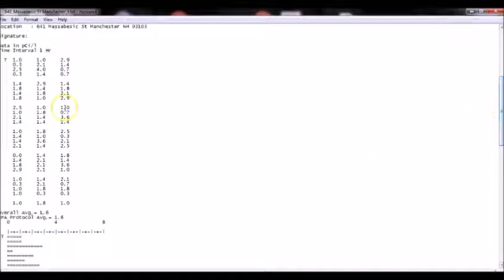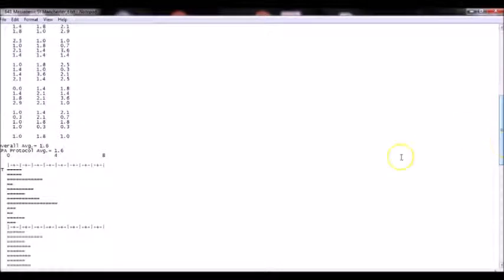Right here is the overall level of the test. This one is 1.6 picocuries per liter. Here is the EPA Protocol Average. That is the number that we use for a real estate transaction. The EPA protocol takes the first 3 hours of the test right here, throws them out, and averages the rest. So for this particular test, the overall reading is 1.6 picocuries per liter.